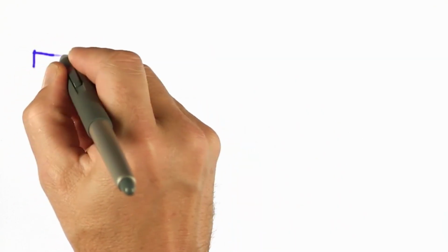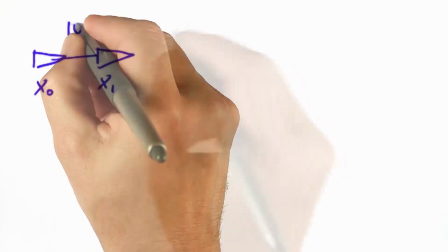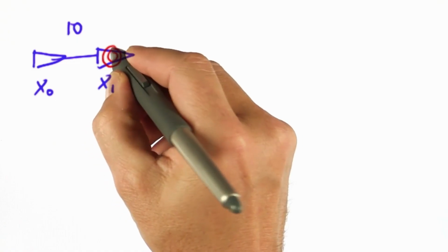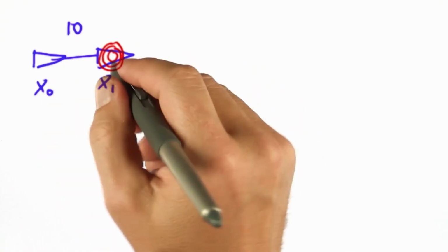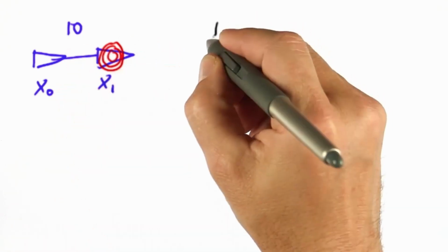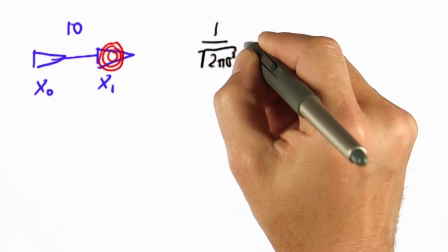Suppose we have two robot positions, x0 and x1, and we know they're 10 apart with some Gaussian noise. In expectation, the Gaussian moves the right robot position 10 off the left robot position, but there is some uncertainty. When we talked about Kalman filters, we talked about Gaussians. And this uncertainty might look as follows.